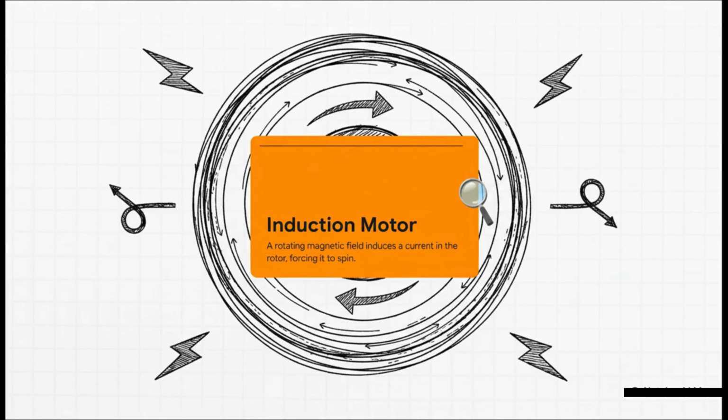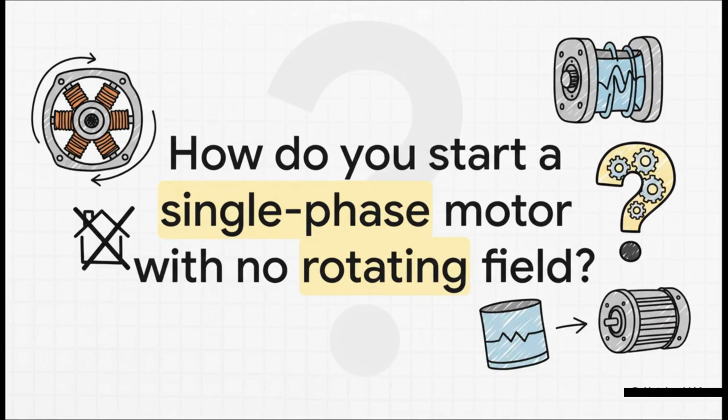The absolute genius of Tesla's motor is how ridiculously simple and elegant it is. Get this. There's no direct electrical connection to the part that spins, the rotor, none at all. Instead, the stationary part creates a rotating magnetic field, and that field induces a current in the rotor, basically making it chase the field around and around. Fewer parts, nothing to wear out. It's just incredibly reliable.